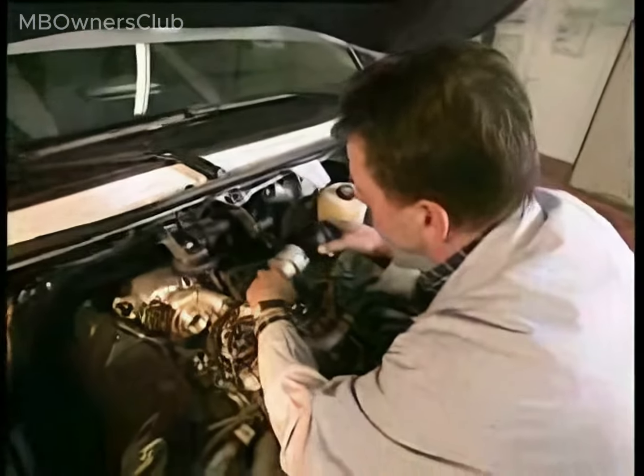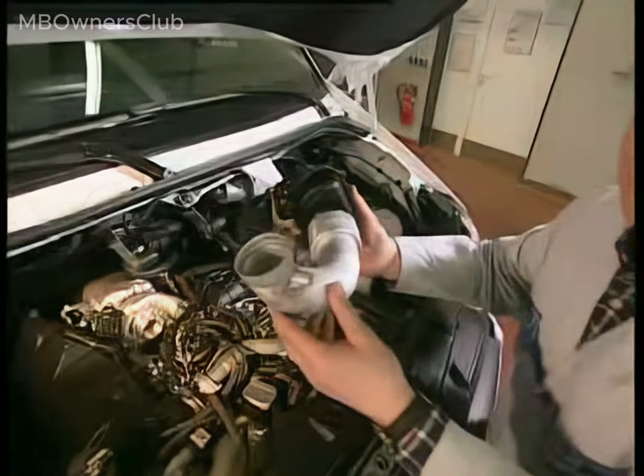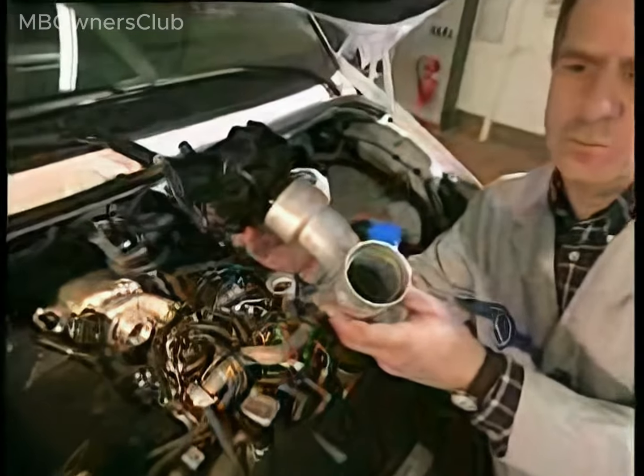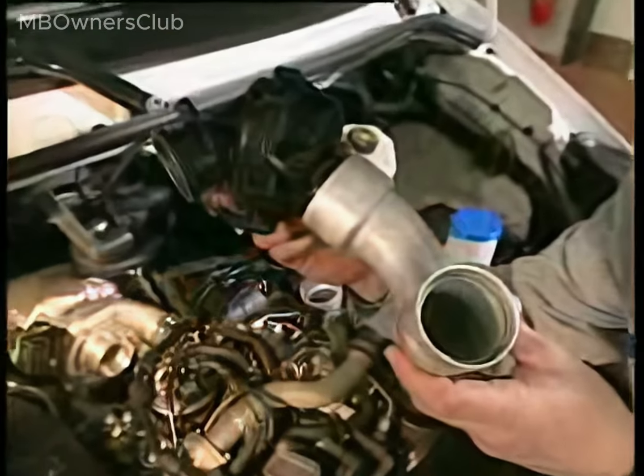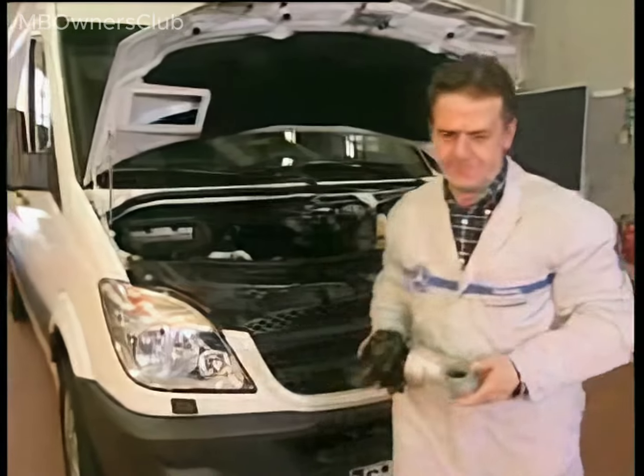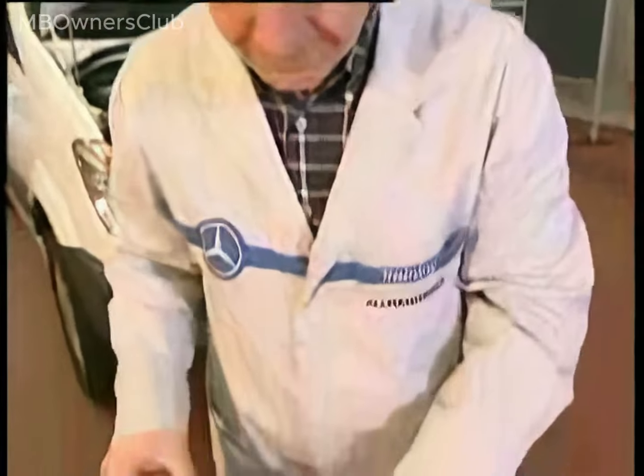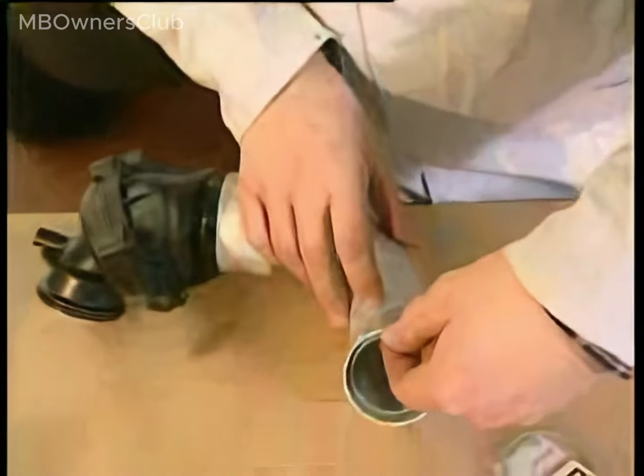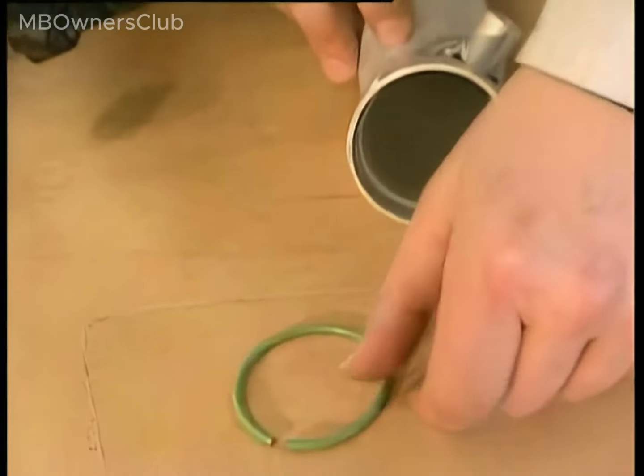Repair. A common cause of leakage is O-rings damaged during installation, located in the pipeline at the turbocharger or at the resonance damper. It is evident here that this seal ring has been cut as well as crushed. The seal ring must be replaced. Install the pipeline and recheck the charge air system for leakage.